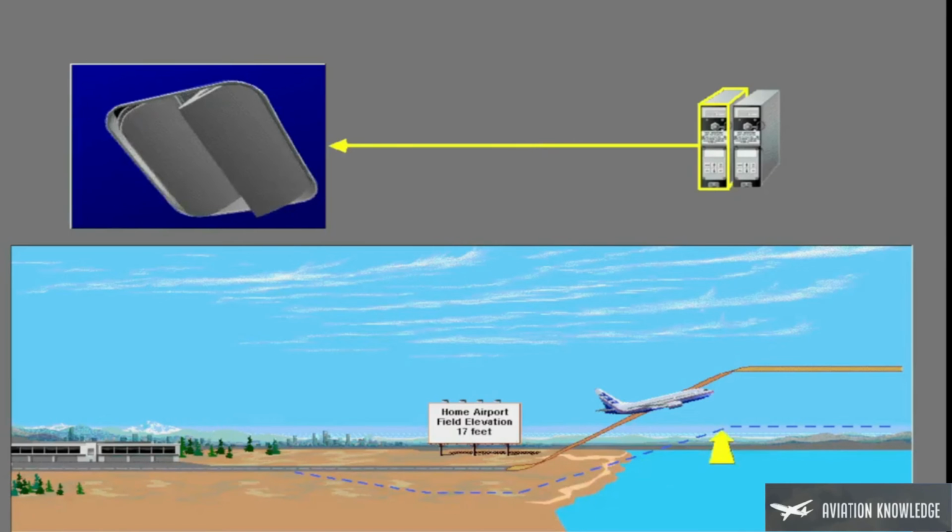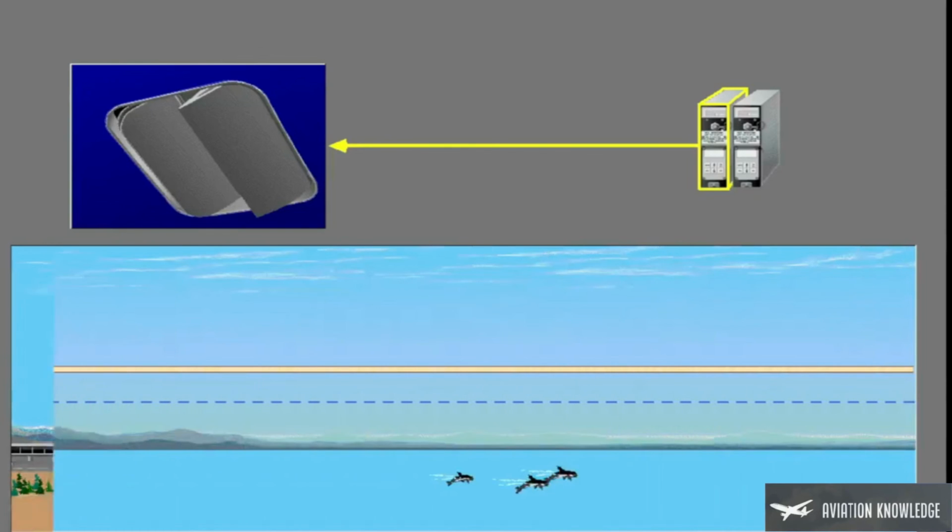While in flight, the pressure controller uses the outflow valve to control the cabin altitude. During climb, it keeps the cabin altitude proportional to the airplane altitude. When the airplane is at the planned cruise altitude, the pressure controller starts cruise mode. Although the airplane altitude may change a small amount, the cabin altitude remains constant during cruise.